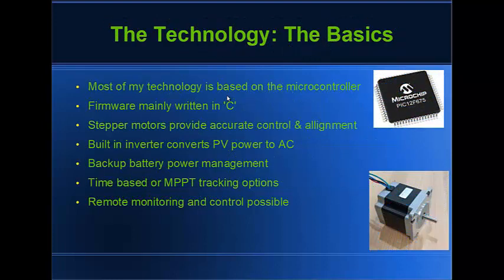Let's just have a look at the basics of the technology. Most of the designs I have currently are based on the microcontroller, and there are very sound reasons for this. Microcontrollers can work out as dollars a piece when ordered in bulk, compared with tens or even $100 plus for a microprocessor. They have very low power consumption. A microprocessor will consume something like 15 watts of power, whereas microcontrollers' consumption is measured in milliwatts. They are much more tailored to the application.